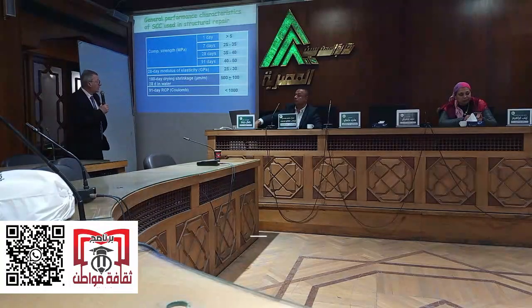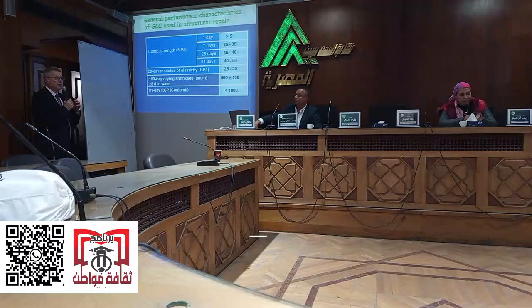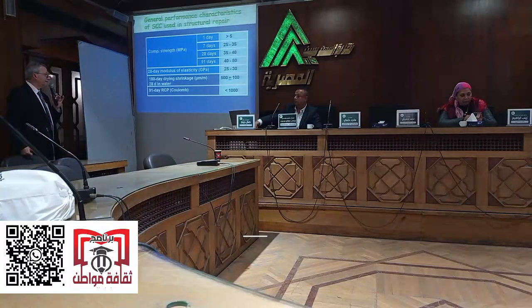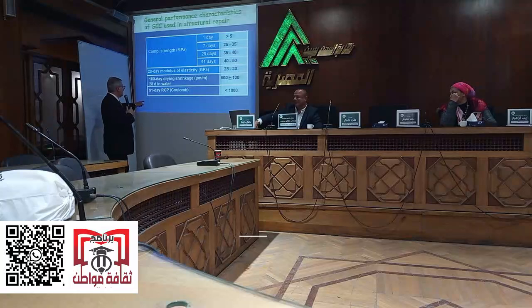Next, mechanical properties. After 1 day, we had 5 MPa, which is important to be able to remove the formwork. But you don't want 20; you want 5, 7, 10 maximum. And you can see the strengths. Again, the strength is not important here. What is important is the workability and durability. You're going faster than me. The RCPT, this is a coulomb value for corrosion resistance.